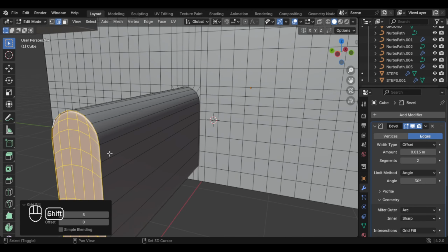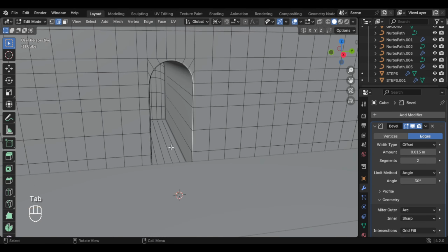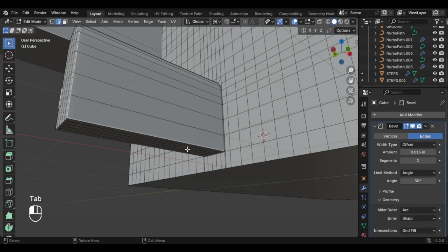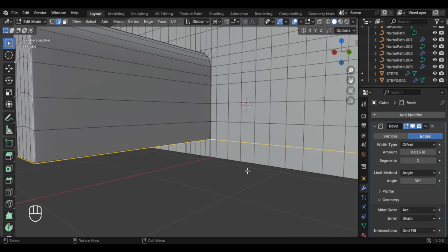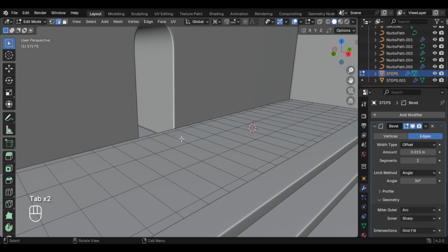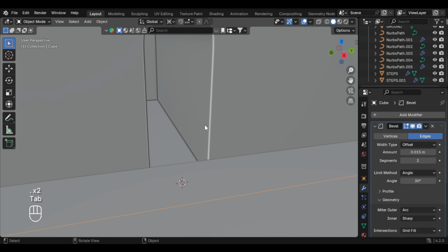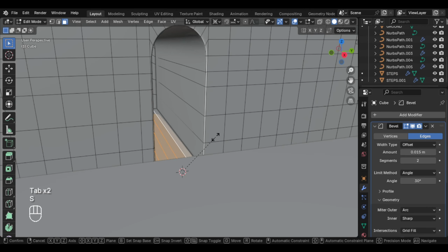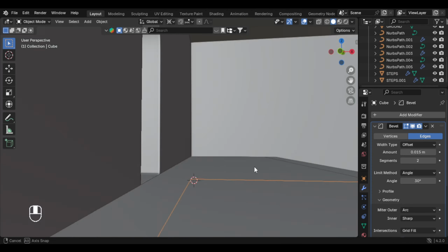And if it doesn't fit, we have to go down here and change the numbers, and we have to also match this ground here, so we can just select these faces here. And what we also have to do, we have to select these edges here, so this whole edge, and let's go to here, and we can select this one, this object, and we can go to 3 and Shift S and cursor selected, and change your period to a 3D cursor, and we can select this again and S, C and 0, and now the ground is perfectly fit to this other one.